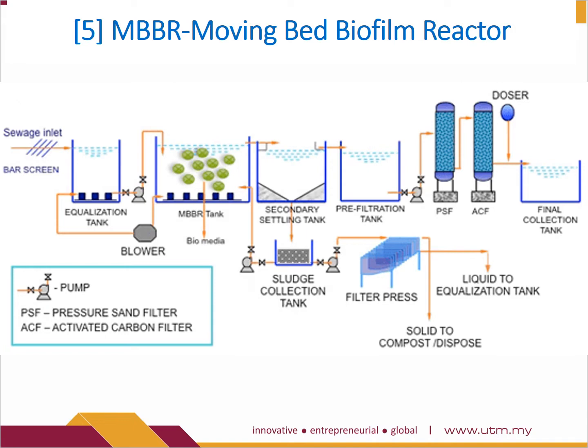It is a thick layer of sand to further remove those pollutants. And then activated carbon. The sand is to remove the very fine solids, and the activated carbon filter is to further purify the soluble contaminants. Dosing is chlorination, and finally it will be ready for discharge.